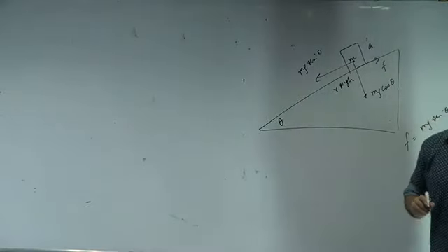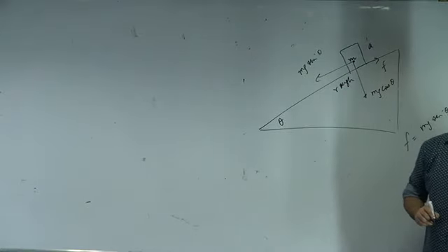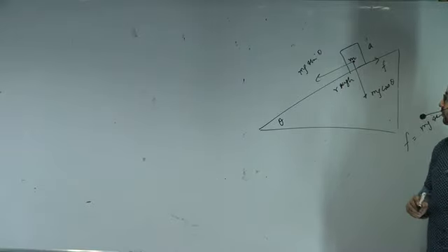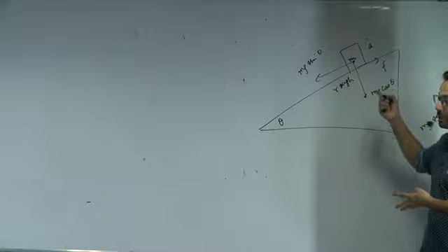What is the torque of mg cos theta? What is the torque of friction? mg sin theta into a by 2, anti-clockwise. Yes, anti-clockwise. So is it toppling?